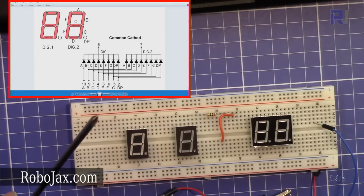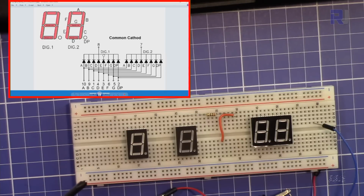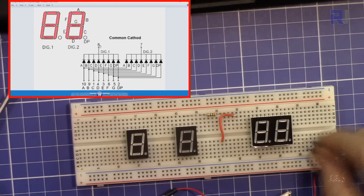So now let's look at the diagram here. We have 2 digits the same way, side by side, decimal point A B C D E F G. Here, the common cathode is the negative, and the anode is the positive. So pin number 10 is A, and B is 9, C is 1, D is 4, and so forth. If you want to turn on digit 1, you have to connect the common to 8. So this is digit 1.